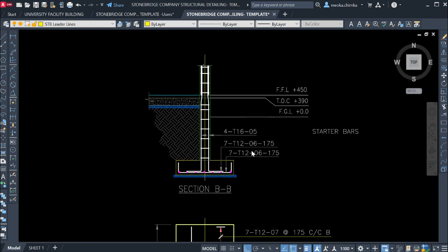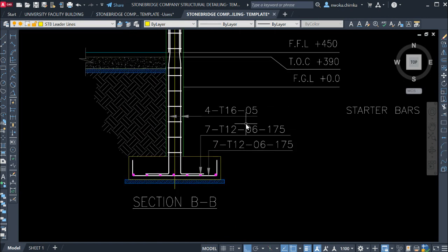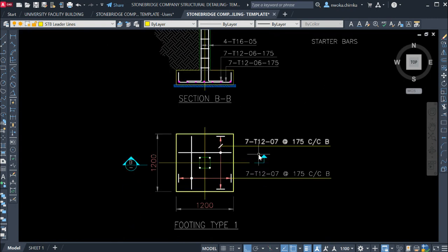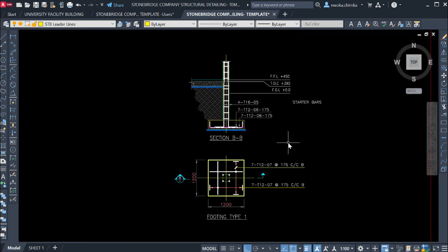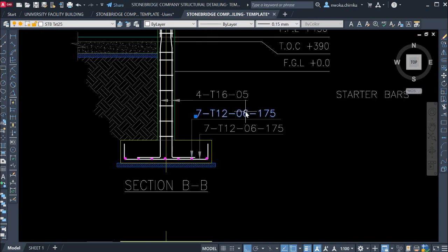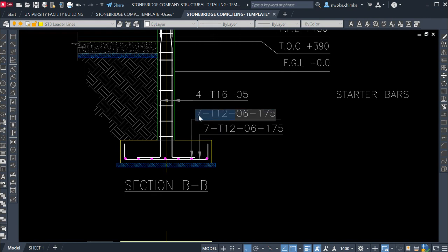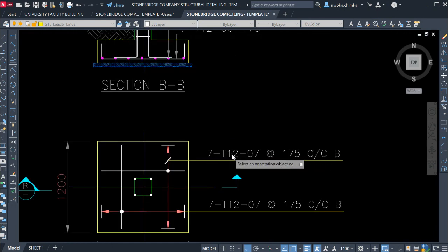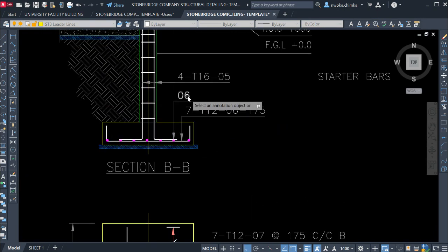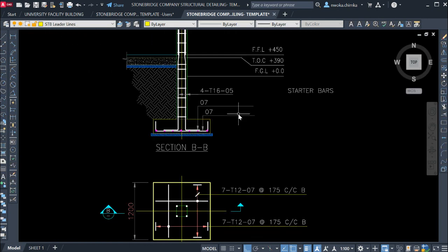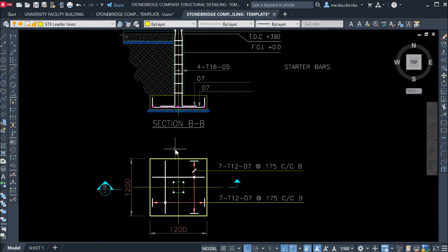And if this thing is giving an issue, instead of showing the total number of reinforcement here, because you already have it on this plan view, as you can see here, let me do my match first, if it's okay. So I'll just show the bar mark which I have here. Bar mark for here we have bar mark 7. Okay, this is bar mark 7. I can see it here, 7 and 7. So I'll change this to 7, so that once they read what they have here, they will automatically know that this is just the cross section